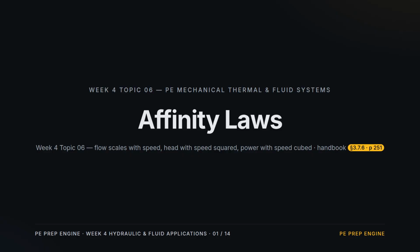Topic 6 of Week 4. The affinity laws, the most frequently tested pump calculation on the exam. They tell you how flow, head, and power change when you spin a pump faster or trim its impeller. The whole topic rides on one pattern. Flow scales with the first power, head with the square, power with the cube. Get those three exponents right, and you own this section.